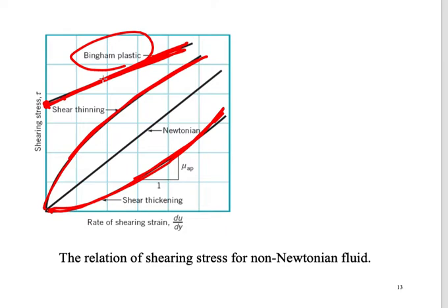For example, we could analyze the molten metal flow into the molding by using the idea of fluid, but we need to modify the equation because it is not 100% similar to the fluid. Because it is a non-Newtonian fluid, maybe the viscosity keeps changing, so it will influence the motion of that Bingham plastic.